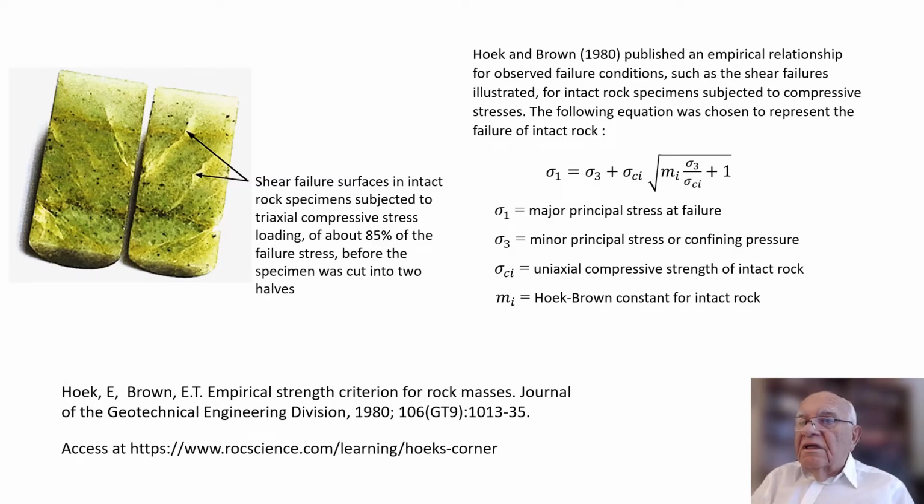The illustration on the left shows two halves of a specimen which was loaded triaxially to about 90% of its uniaxial compressive strength before cutting it in half and polishing the surfaces. Shear failure cracks are visible in the polished faces of the specimen.